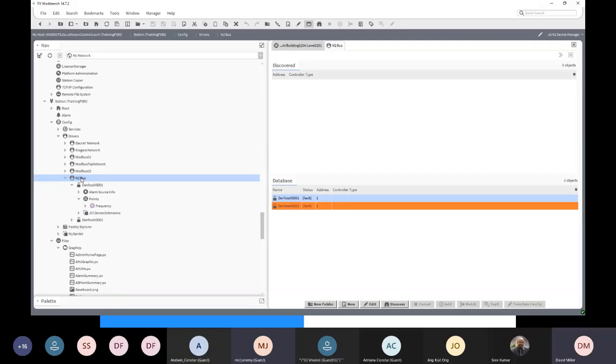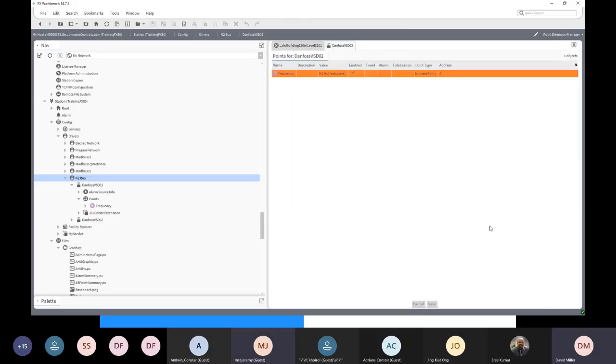So when you say you changed the device address, did you change it in here? For example, my device address is 4. Then I can discover it, I add it, but I cannot show online. Then using the Metasys, I cannot troubleshoot it. So I just try my luck to change the address, become 6, discover it, and become online. So is it possible on the FX server to make a troubleshooting on this kind of problem?